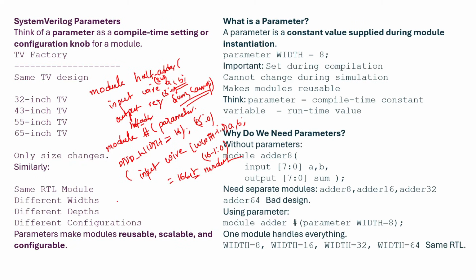Then during the TB time, we are using different bits. Then we can override the bits, right? Based on the tick defines, defparams, and then some constants directly passed. Based on that, we are changing the bits.